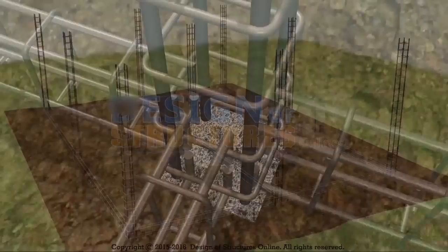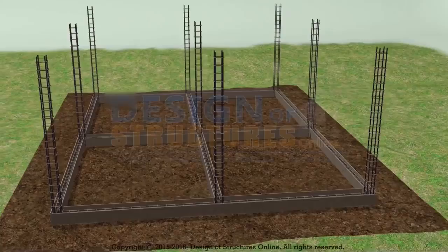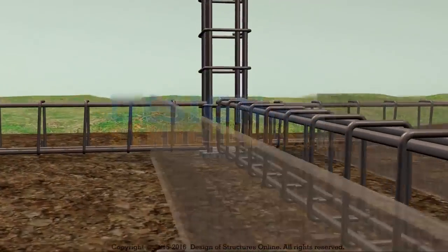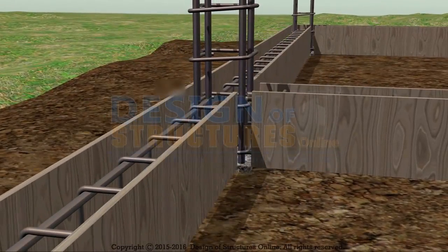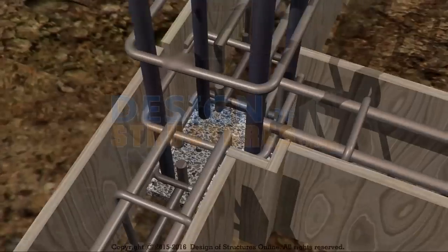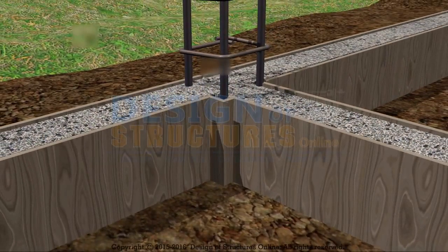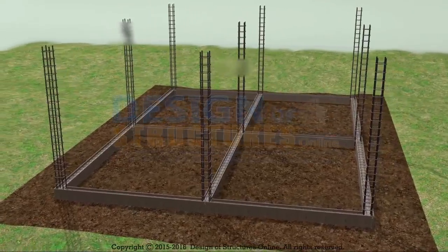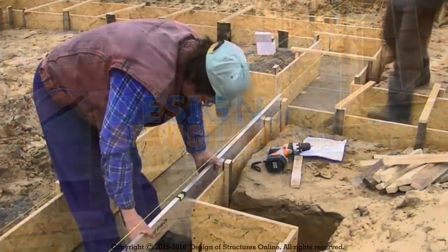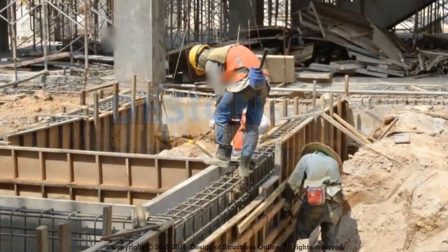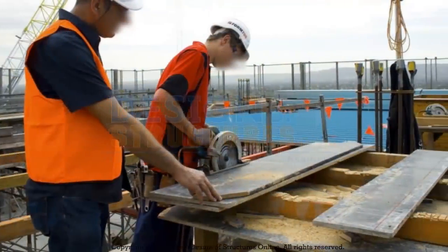Joints in the beam shuttering should be tight against leakage of cement grout. Construction of shuttering should permit removal of various parts in desired sequence without damage to the concrete. Beam concreting. Beam is poured with concrete of the grade mentioned in the drawings. The positioning of reinforcement should be properly aligned. Shuttering parts and connections should be arranged in a way that makes formwork removal easy and simple, and prevents damage to concrete and formwork panels so that they can be reused without extensive repair.